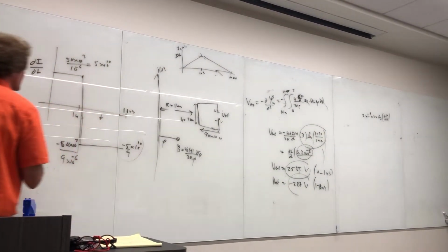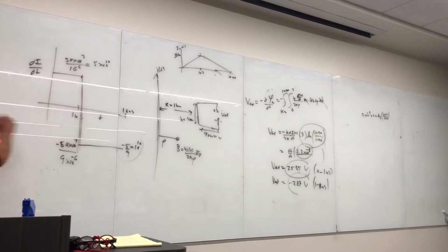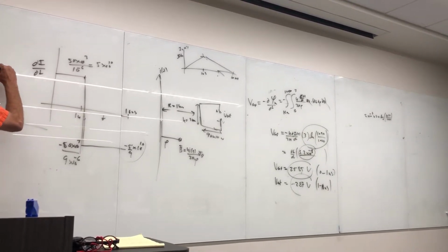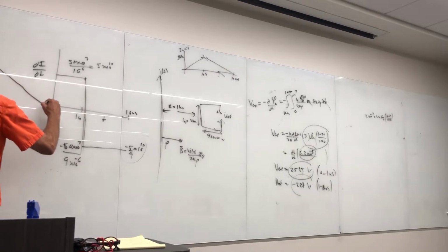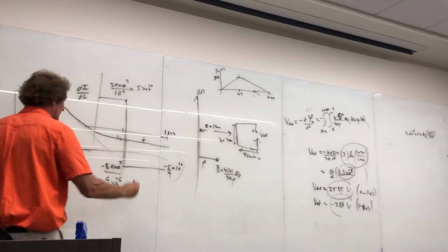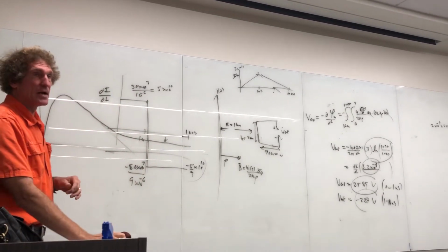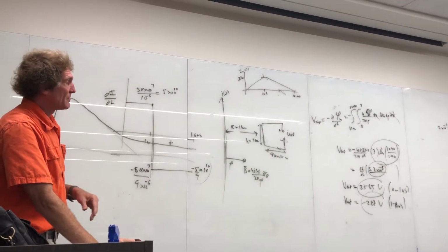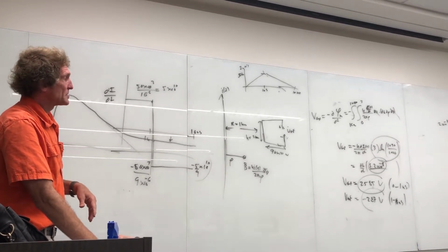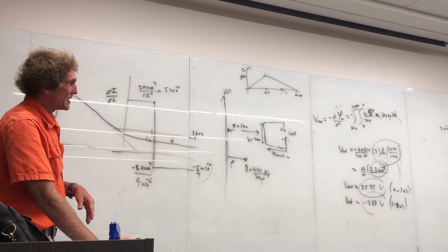The real lightning waveform looks more like this. It's a double exponential. It comes up, crests, and then it'll start coming down, and then there'll be this long duration tail on it, but you can sort of asymptotically click it down there. And that's about the kind of voltages you can expect to induce on this simple loop on a house that they try to estimate.